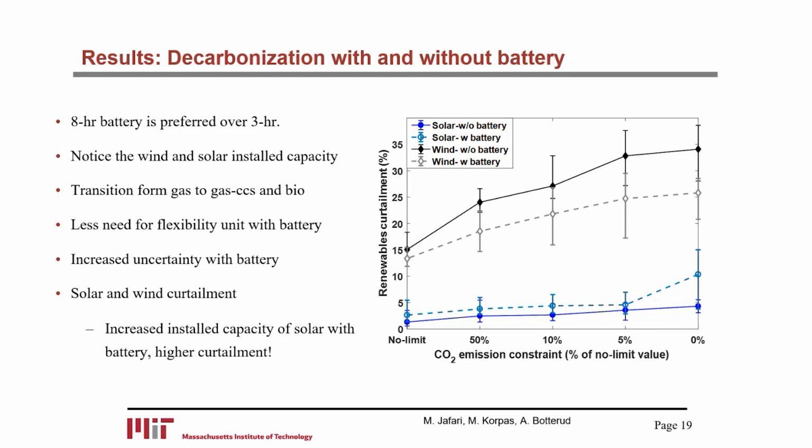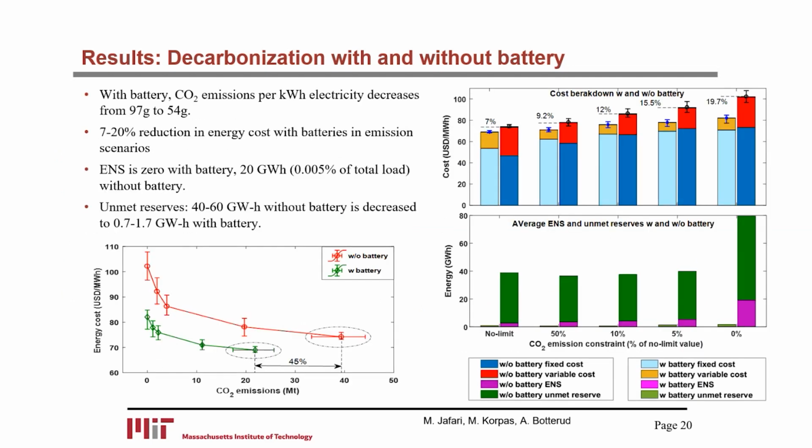Yes, isolated, it works like that, but if you look at the long-term cost minimized system, it's better to build so much PV that more of it is actually curtailed when you don't need it, because during the rest of the year it's beneficial to have this amount of solar power installed. So more batteries, more curtailed renewables. That's a finding. I hope it's correct.